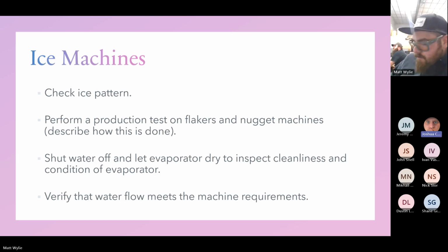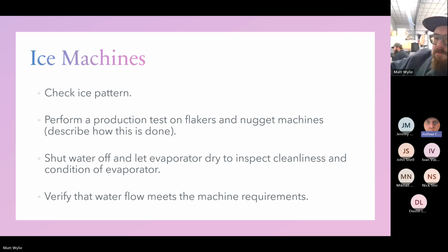Yeah, usually the letter indicator on the refrigerant will tell you what temperature range that refrigerant will do. Which letter? After the number, usually there's a letter, like the 507A, that's a low temp. But usually when I see a 404, I think it's going to be a low temp because primarily that's what it is.